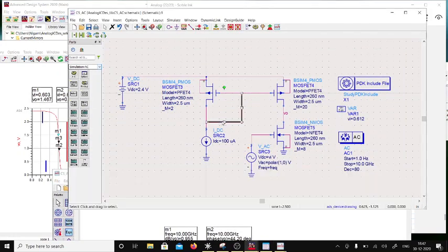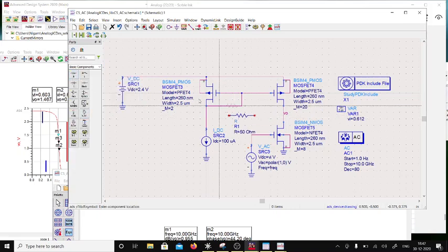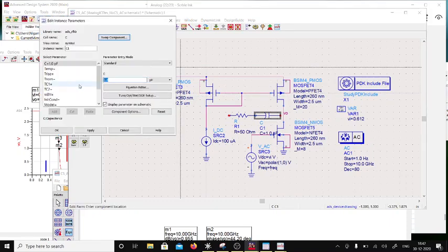I will go into a separate session on compensation, but here I'm going to do a lead compensation, and that too I can derive, but for now I'm just going to give you a direct lead compensation here. So I am going to choose here. Now these capacitor values can be tuned. So I'm going to start with 50. Sorry, I'm going to start with 50. So this is 0.5 picofarad. So I'm going to start with 0.5.